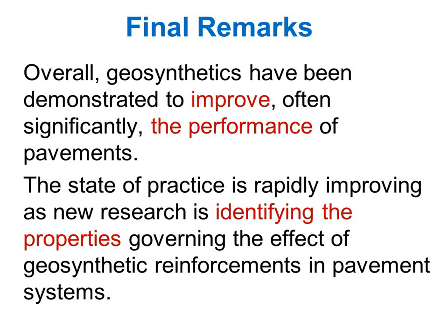So what we're really testing is a confined geogrid submerged in oil. We have done separate testing to evaluate the potential effect of having oil versus water, and what we concluded is that there is a small effect because there is a viscosity issue. But that has more to do with the time response of some of the displacement behavior. In terms of load responses, it's very similar.